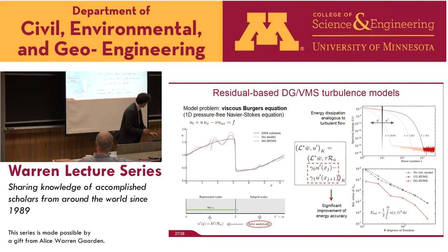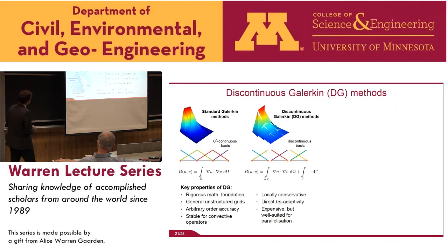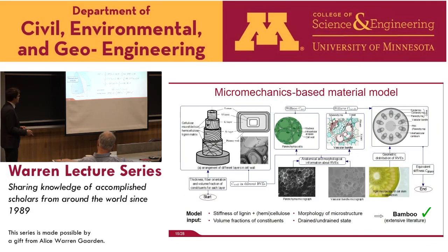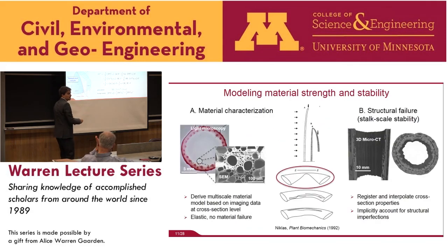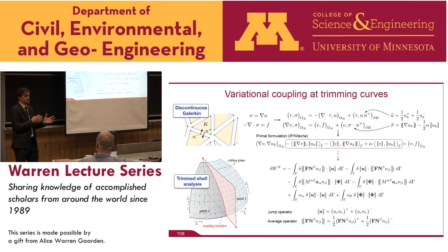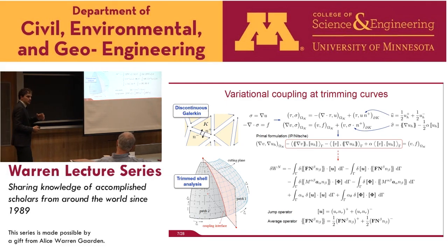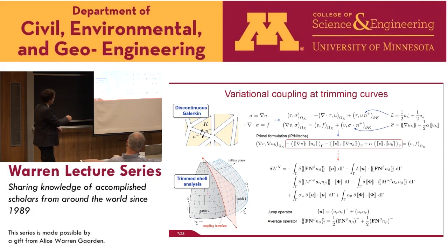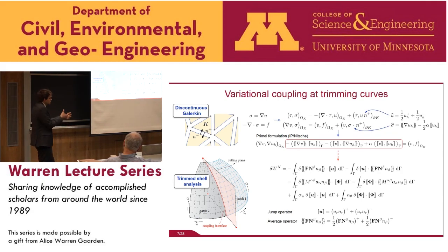So let's look at this one. Here the idea is that there exists a method to automatically choose these stabilization parameters. The stabilization parameters you're talking about are these alphas here. If you're using your weak form without these stabilization parameters, you could lose, in the worst case, coercivity and stability. So they need to be large enough. You can use that coercivity relation, including these terms here, to consistently derive conditions on these alpha terms. And with some numerical analysis tricks, you can transfer the problem of choosing alpha explicitly into an eigenvalue problem that involves cut elements. So you can choose them from a local eigenvalue problem. You can come up with a minimum stabilization parameter that will make your method work.